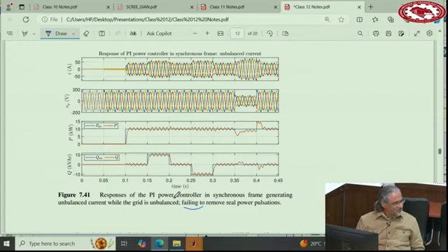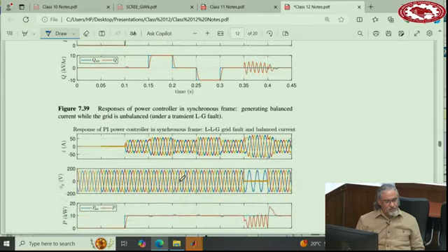The negative sequence component you are not regulating. If you see, only D components are regulating, but to make the pulsation 0, you need the negative sequence component to be present in the current. So I think those negative sequence components are not being regulated perfectly. That's why this pulsation is there. Okay. Let me see what I've explained here.